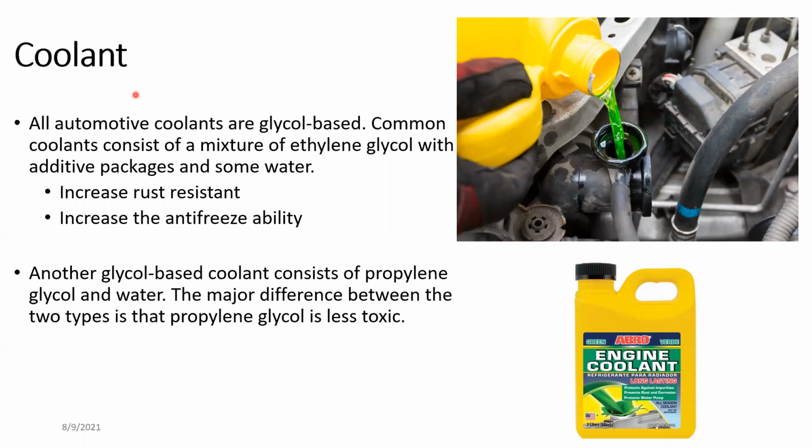So what had to be done is to have a coolant with some sort of antifreeze ability. In order to give this antifreeze ability, coolant was developed. In addition to the antifreeze ability, it also gives resistance to rusting. If water is in the engine bay, it ends up rusting. The engine block and engine head are not going to have any problem with rust because they are either cast iron or aluminium. But the rust is going to be a problem for the water pump.